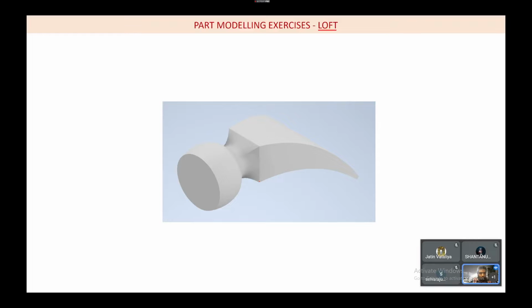So I start the sketch. Now I'm starting the sketch in this vertical XY plane. I start with a square, so I'm going to do a center point rectangle. So we have to choose the center and give the dimension. I'm giving 60 mm width, 60 mm height. So we'll see what we are getting. So like this, give the finish sketch.